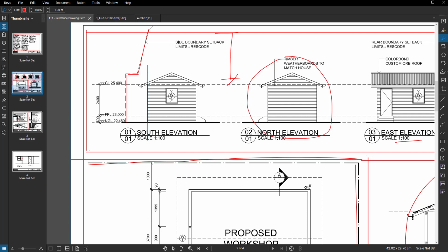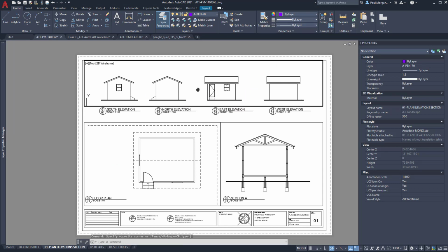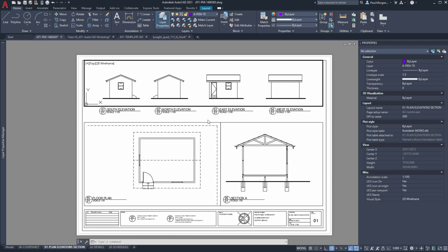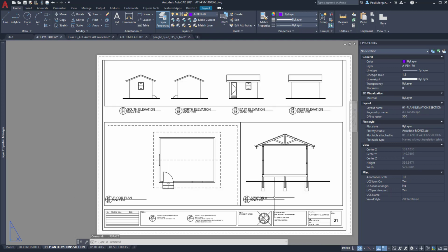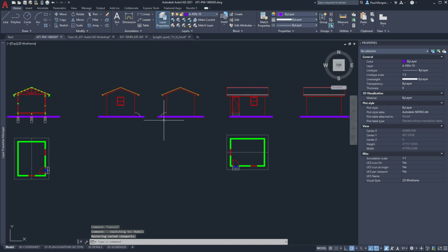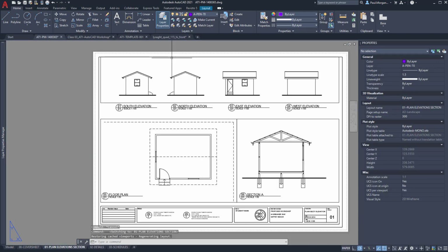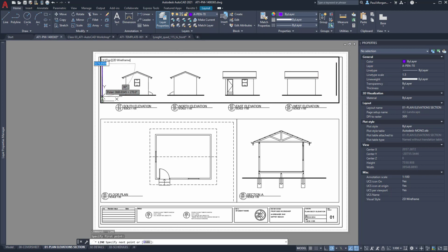So I'll go back to AutoCAD again. And I'm going to drag this down a little bit. The other thing I want to make sure of is that I have relatively even space between these. So it's not wise to model within this viewport. What I would do here is click on this tab to go back to paper space. So now I'm out of that zone. Go back to the model environment and edit the model appropriately here. So a good tip and a good trick is you can go back to the sheet, double click in this viewport, take a line, draw a random line on one side and a line on the other side.